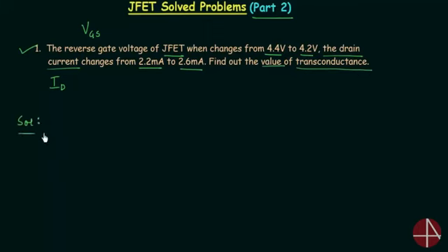what transconductance is. Transconductance is represented by g subscript small m, and if you remember the hybrid pi model lecture, we discussed what transconductance is. Transconductance is equal to the ratio of output current to the input voltage for constant output voltage. Very simple.